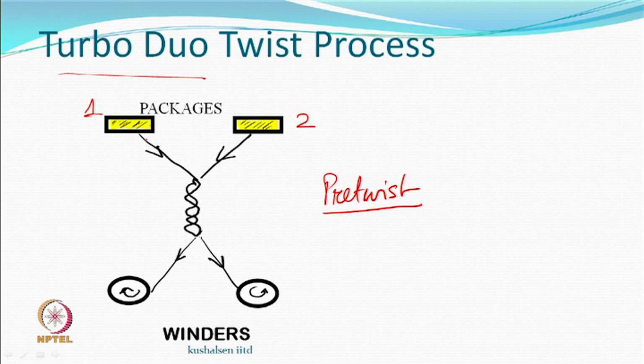So, what you have is, actually you should have a feeding mechanism. Why is this feeding mechanism required? What is important is that if you do this and just keep pulling, as long as the yarn is being fed, you will suddenly find this twisted zone just remains there. The new yarn comes in the zone, gets twisted, and as it gets out of the zone, that portion where the twist is there, it just stays there, maybe a little bit of vibration based on what you do.